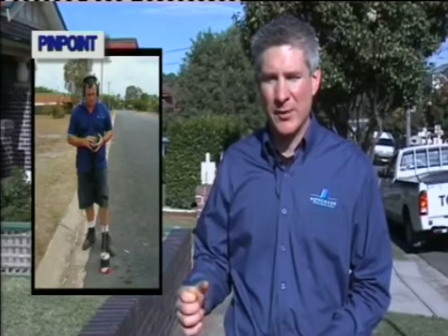Now if the leak had been under the road or the footpath, we would have used the ground microphone. And the ground microphone is used by simply placing it on top of the road or the footpath and moving it back and forth until you find the point with the loudest noise.